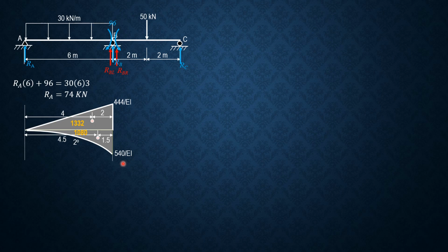So remember that the deviation of B relative to A is the moment of areas between A and B with respect to B, while the deviation of A relative to the tangent at B is the moment of area with respect to A, from area moment theorems or method. So this is the beam, and let's draw the elastic curve exaggeratedly later.